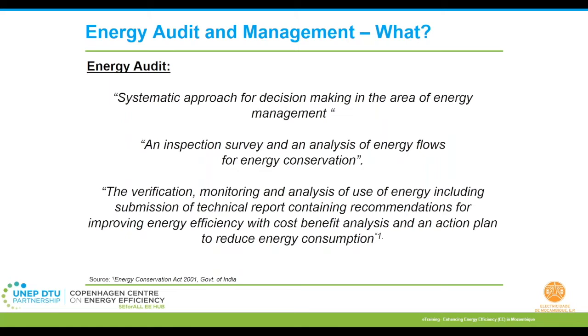It contains analysis of all the energy use, and also includes submission of a technical report, which contains recommendations about improving energy efficiency, along with cost-benefit analysis, and then also an action plan on how to reduce the energy consumption. So it's not just about identifying the measures. It's also about how you monitor, how you verify it, and then how you implement it with an action plan.